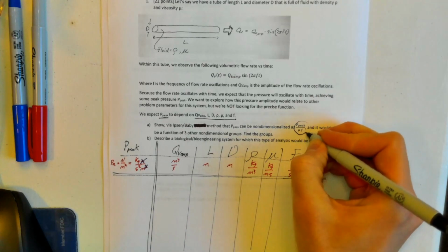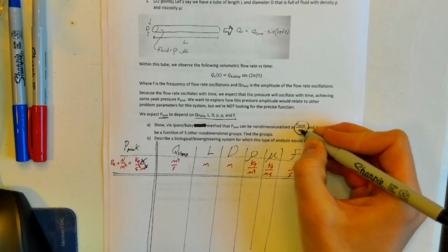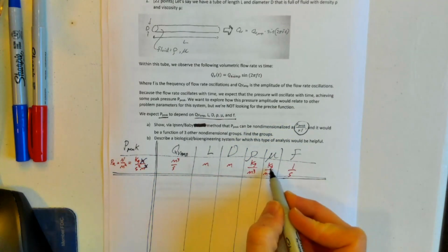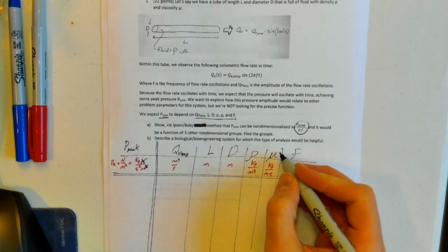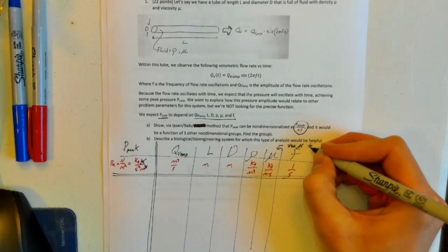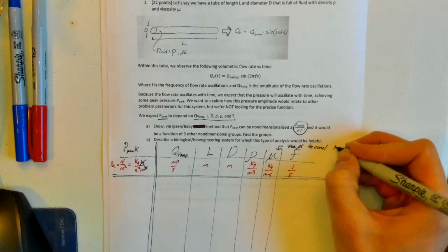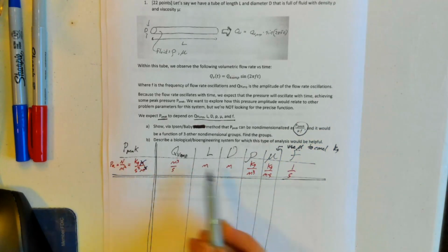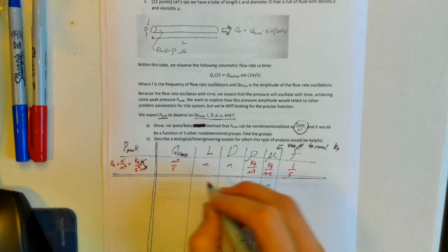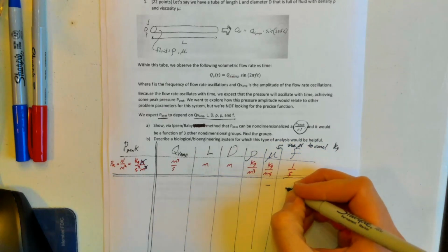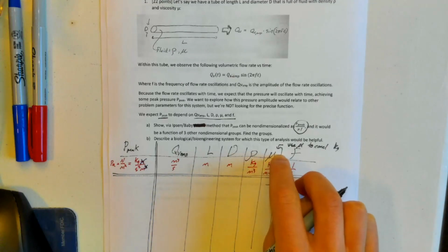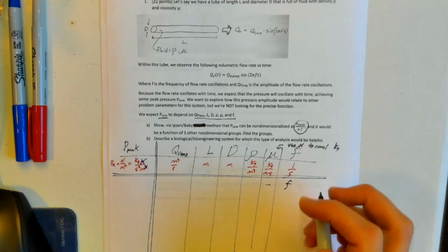We see here that we're looking on our left-hand side to have peak pressure divided by viscosity as one of its terms. Well, viscosity has kilograms right here. So we're going to use viscosity to cancel all instances of kilograms for things both on the left-hand side and the right-hand side. All right, so now we've gotten rid of viscosity because we're now using this in other groups. Frequency doesn't have units of kilograms, so that's just going to stay how it is. We notice that density has units of kilograms, so if we divide density by viscosity, the kilograms in both of them will cancel out.